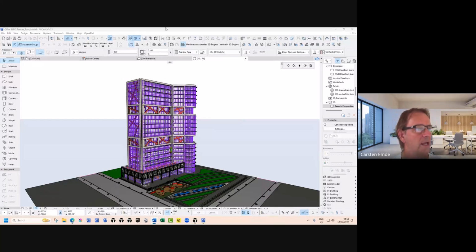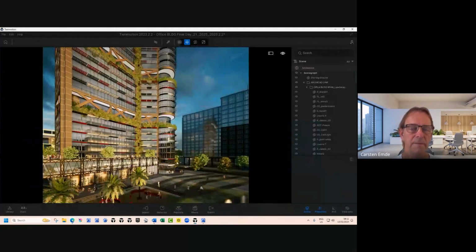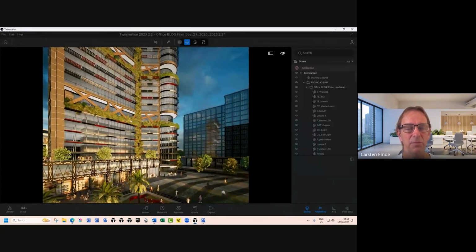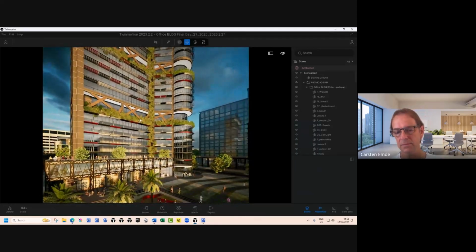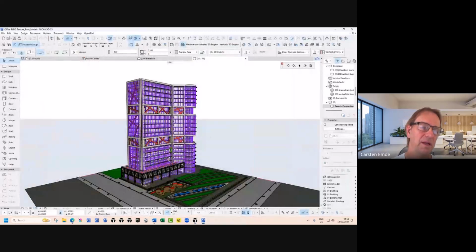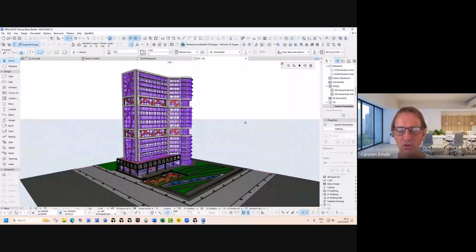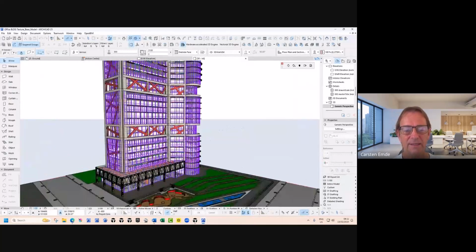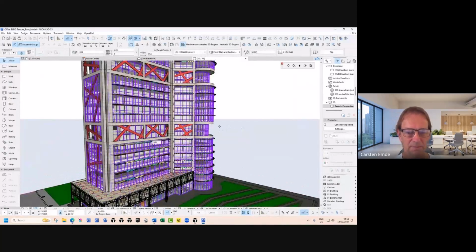Okay, cool. So I shared my screen. I'll start with a high-rise model I've got here, and I do have this in Twinmotion. What I'd like to tell you about is the split up of materials. I know you probably know yourself, you have to split up the materials in ArchiCAD because of applying materials in Twinmotion. So I'm sure that's fine. But what I'm getting at is that you should consider sometimes splitting up materials in the model, especially in this. This is a good example of a high-rise.